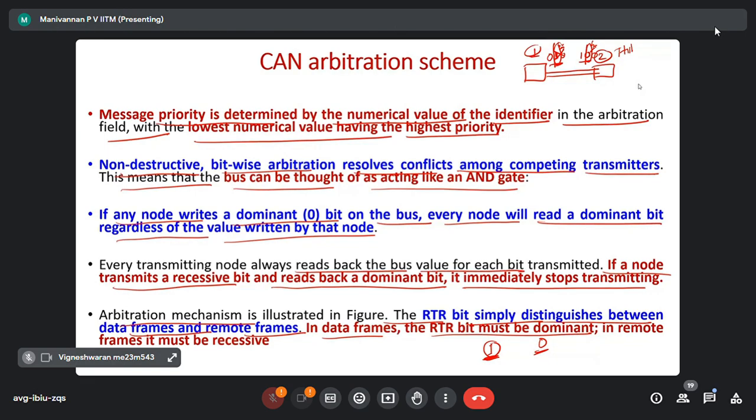Right. Correct? Right, so sir, thank you. All bits can be 1, 1, 1. See, you never send all 64 bits like that. Engine speed is full, torque is full, all 16 bits, no. By fluke it happens, because the data value can vary. So 64 microseconds should be the idle time. After that at least, the frame should be transmitted. Otherwise, in between itself, there are chances data collision can happen. Arbitration is always done during the identifier duration only. After that, just transmission. Data, CRC, everything will be transmitted.